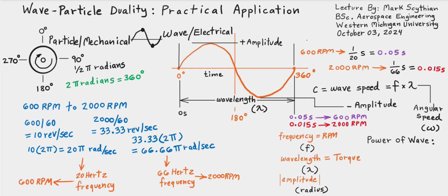So we'll assume that we have some constant torque, i.e. constant current, and then we're able to change the RPM. So you can think fundamentally like this. If you end up getting one of those questions where you're designing a sensor or even doing the stress analysis, and right away they say series, you're going to be like, nope, that's a constant torque, constant current, because energy is not created or destroyed. So what happens to what's correlating to current? It's going to be the torque. What's correlating to voltage? It's going to be RPM.